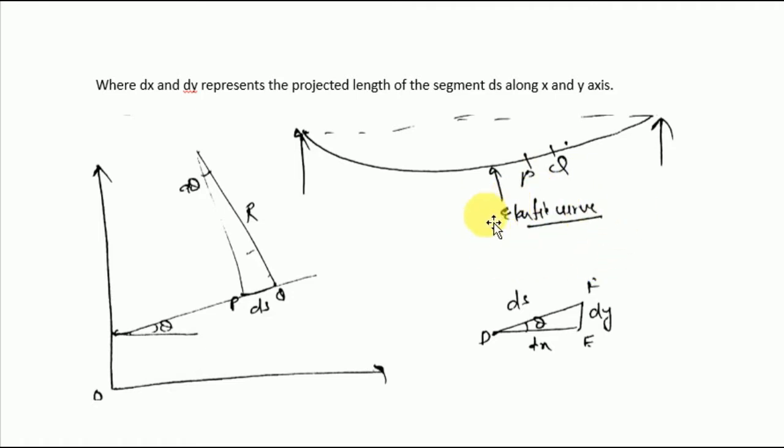To find a particular equation that describes the behavior of this elastic curve, so the slope and deflection of this beam can be analytically analyzed, we cut a section PQ of this elastic curve and analyze this part.